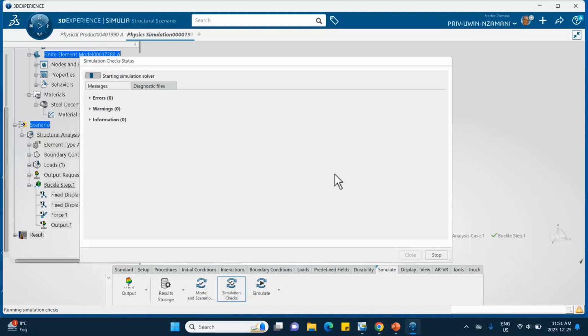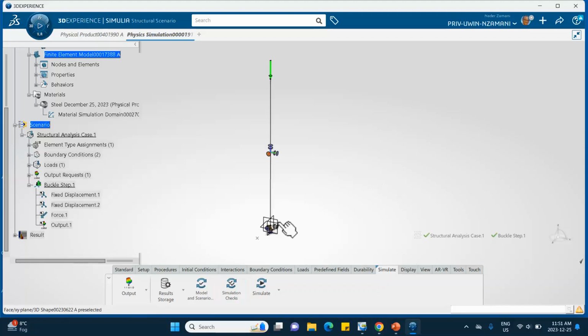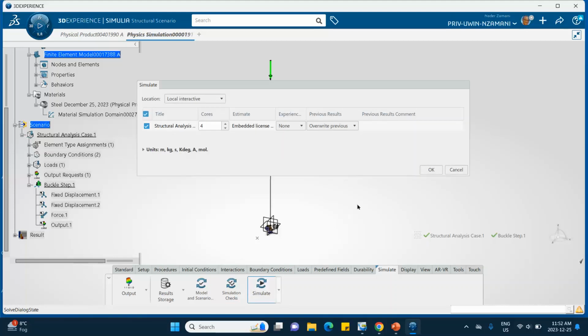It's a good idea to read these warning messages, but that's fine. It says that buckling is not supported by this algorithm, which is fine. You don't need it. So simulate. Now this is where it's going to run and extract the first 10 frequencies. Not frequencies, buckling loads.